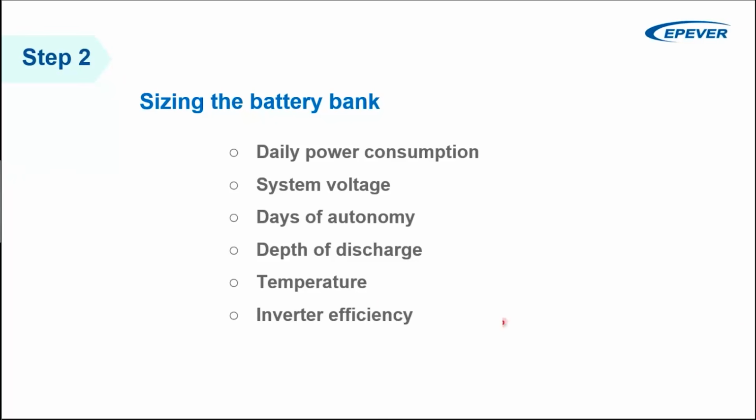And of course, the depth of discharge is also used for designing the battery bank. Besides the voltage and capacity, the other primary design decision is how much to let the batteries discharge. The more the battery is allowed to discharge, the shorter the lifespan is. While allowing batteries to discharge more seems cost effective, this way the batteries won't last long.